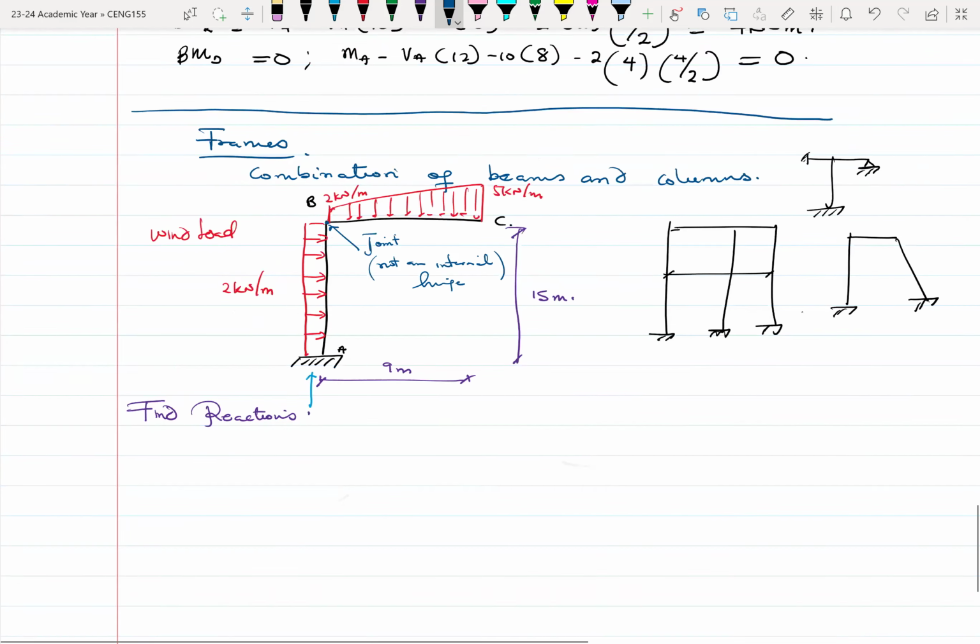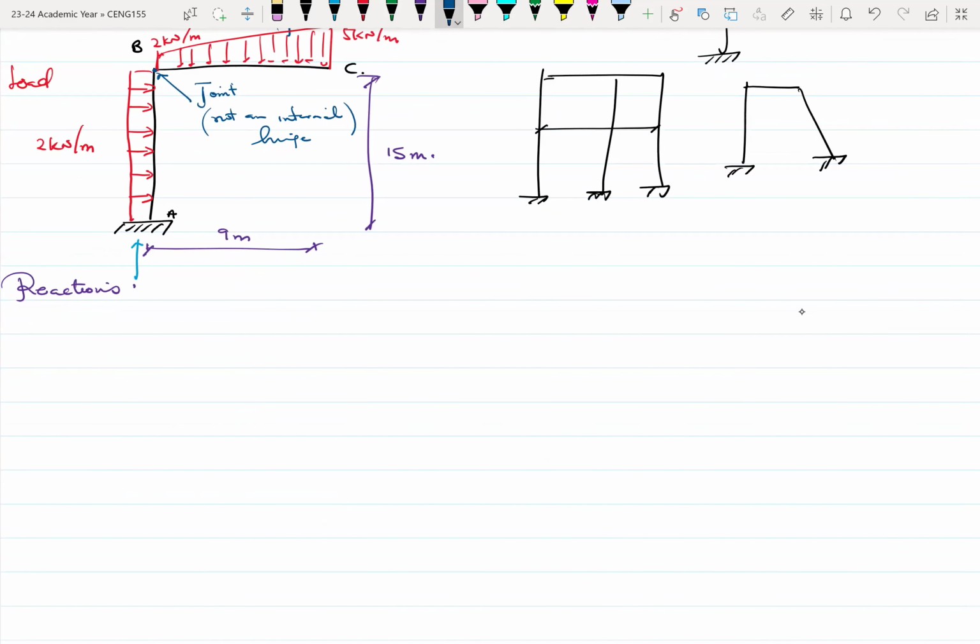All right. So for example, let me just sidetrack a small bit. If you have this beam here, this is statically determinate, right? And you place an internal hinge over here. It means that your unknown reactions are 3. Your equations are now what? 3 plus 1. And since E is more than R, this is unstable. What this means is that if you apply any loads to the system here, it would undergo a mechanism. So your beam goes this way, it just bends down like that, and then failure would occur. So when we are adding internal hinges, we are careful as to how we add them so that we don't end up creating some failure mechanism.